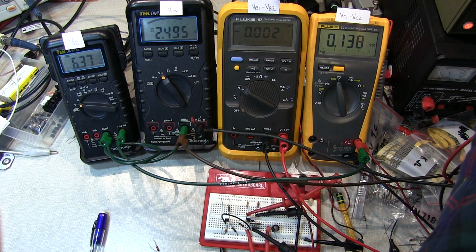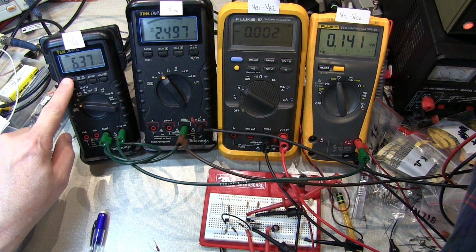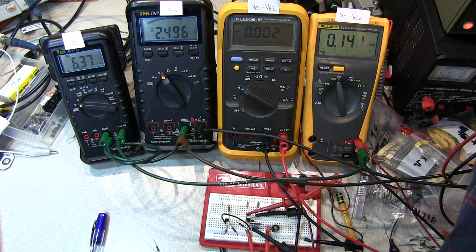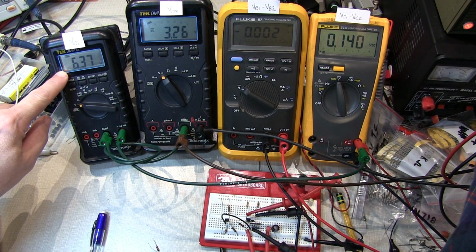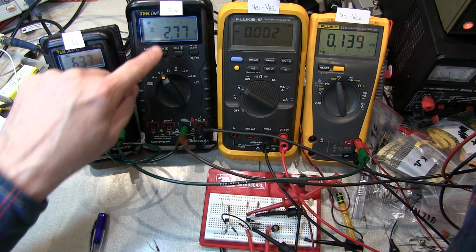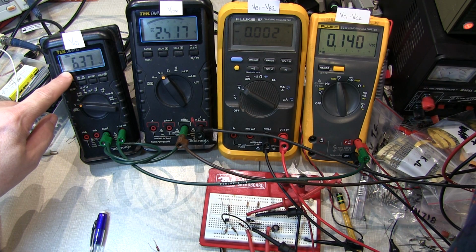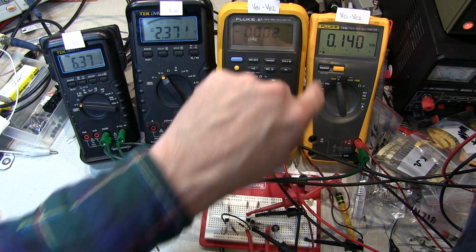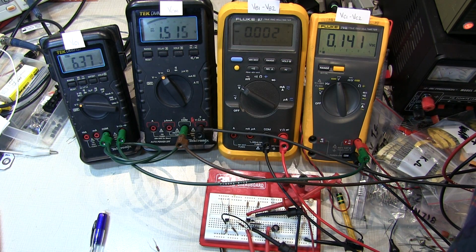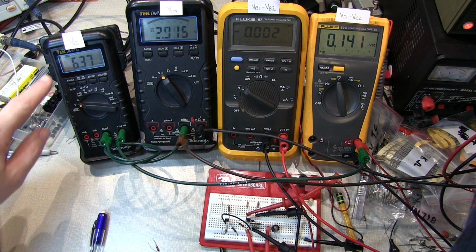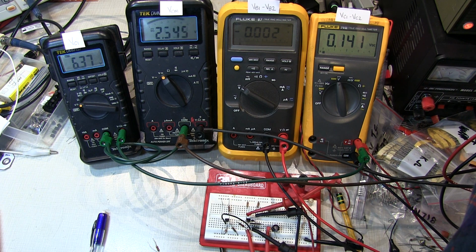If I reach over here and change the common mode voltage, watch what happens to the difference voltage and my output voltage here. So let's go up to, so I'm even at 3.26 volts. My collector voltage didn't change. Let's go back down, 2.77, 2.5 or so. If I keep going down, 1.9. My collector voltage is not changing at all. Okay, my output voltage difference is not changing at all. So now even with large changes in input common mode, the common mode and the collector voltage is not changing at all on our diff pair.